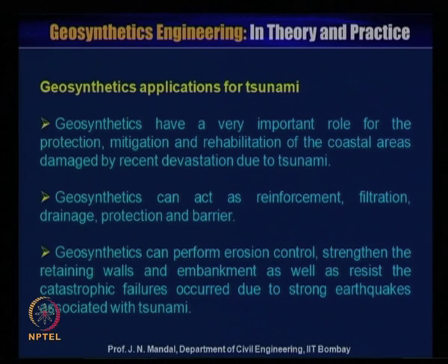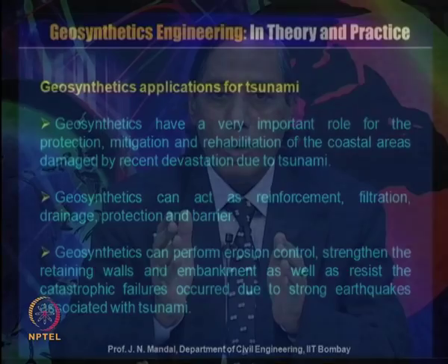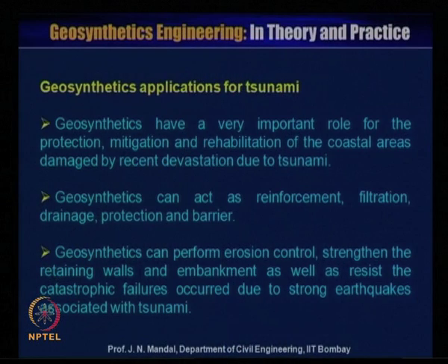Now this is geosynthetics application for tsunami. Geosynthetics have a very important role in the protection, mitigation and rehabilitation of coastal areas damaged by the recent devastation due to the tsunami. Geosynthetics can act as reinforcement, filtration, drainage, protection and barrier. They can perform erosion control, strengthen the retaining wall and embankment, as well as resist the catastrophic failure that occurs due to the strong earthquake associated with the tsunami.